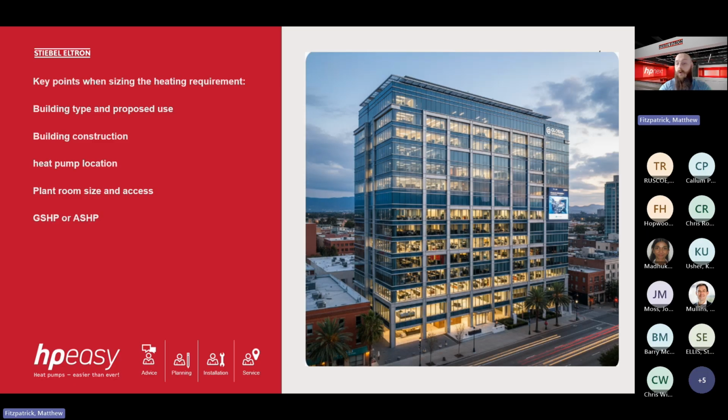If this was a more rural application, we may find fields or grass areas around the commercial building. That could then become a ground source heat pump rather than an air source heat pump. But we'd still need to ensure that the access to the plant room is sufficient. It may be a remote plant room, which is a building just behind the commercial property, designated solely for the purpose of housing the equipment for the heating system, the hot water, and potentially the ventilation.